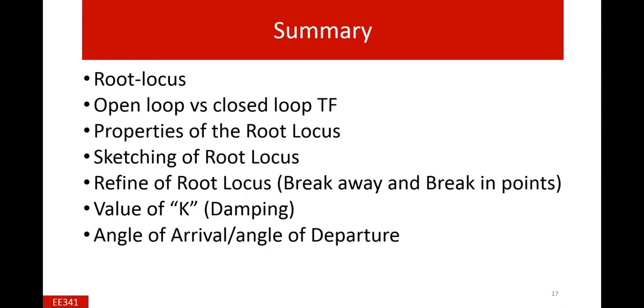And this is the summary here. In this main root locus topic, starting from some simple examples, we found the root locus of some complex planes, and how to sketch where the real axis root locus is lying. We find that for negative feedback, if the total number of zeros and poles on the right half of that region is odd, then there is root locus on the real axis.